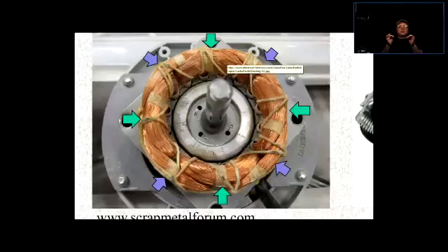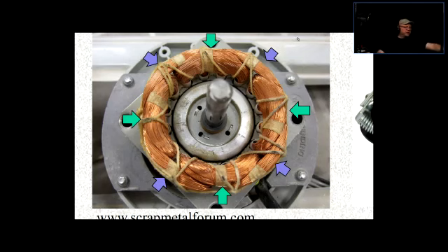The speed, of course, is going to decrease, decrease, decrease, and it's going to go slower, slower. And then at some point, you're going to hear that click. That's the centrifugal switch closing back again. You're not going to hear it opening because there's going to be too much noise, and the opening is just releasing things outwards, and there are all other noises happening, so you will not hear it. But when you turn it off, it's going to go click.